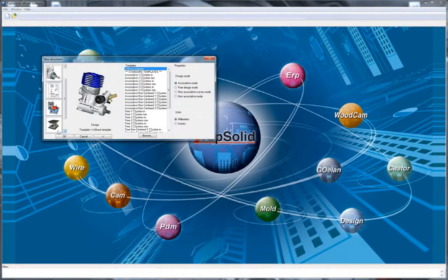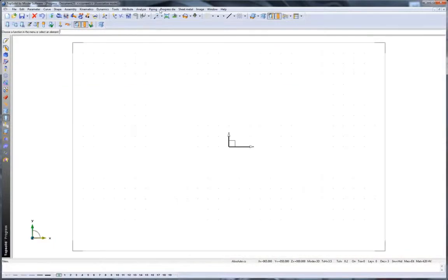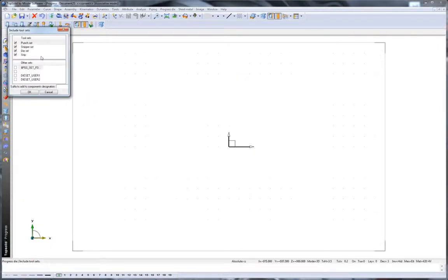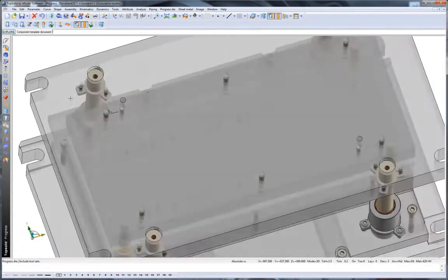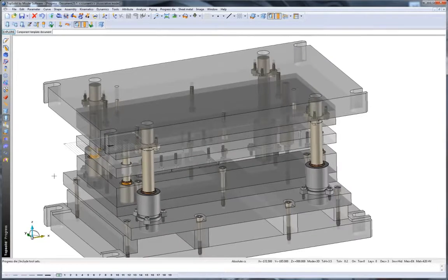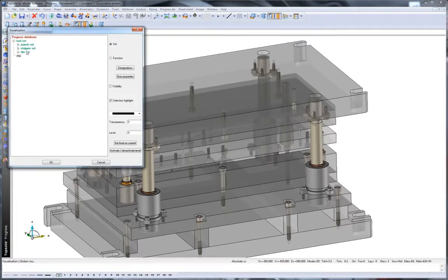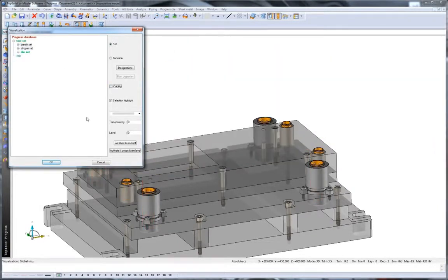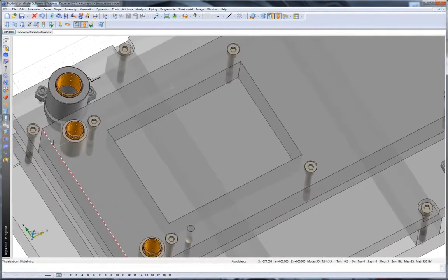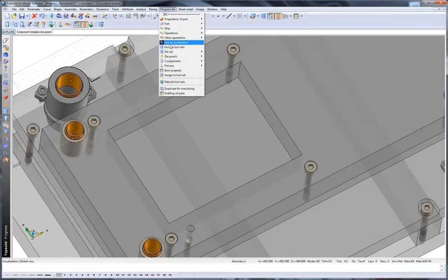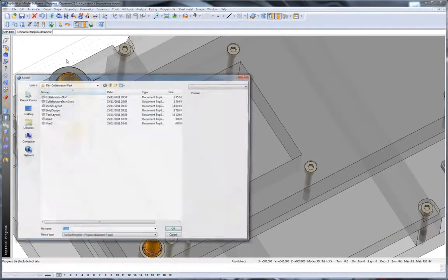Now it's up to the engineering manager to bring it all together, or the lead designer. So here we're going to start by including that original die set. And we're going to turn off the strip because we don't want to see it. So here we see that die set included. Now let's maybe turn off the top two sets. You can see our pocket exists from earlier on. And now we can include the work of User 1 and User 2.